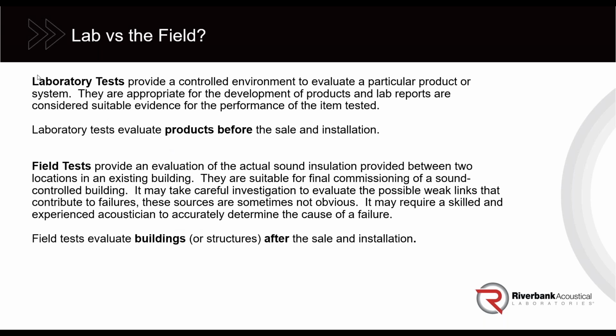One thing to remember, whenever you hear these ratings, STC, NRC, IIC, these are all lab test results. These are not field tests. There are field tests that are similar, but they have different classifications. So an acoustic requirement for an STC rating is asking you for a lab test, and that typically is sponsored by the product manufacturer, although we're seeing more and more project-specific mock-ups for a specific building.